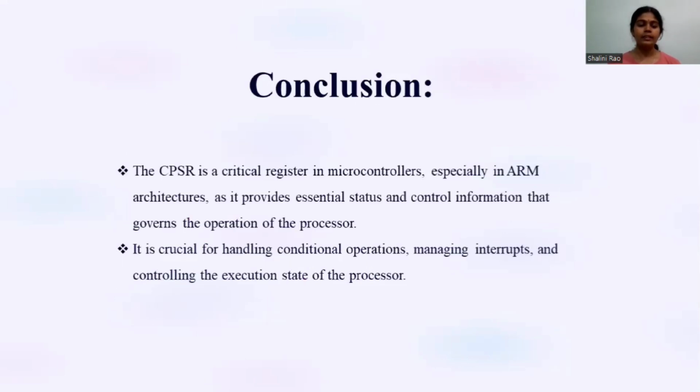Conclusion. The CPSR is a critical register in microcontrollers, especially in ARM architectures, as it provides essential status and control information that governs the operation of the processor. It is crucial for handling conditional operations, managing interrupts, and controlling the execution state of the processor.